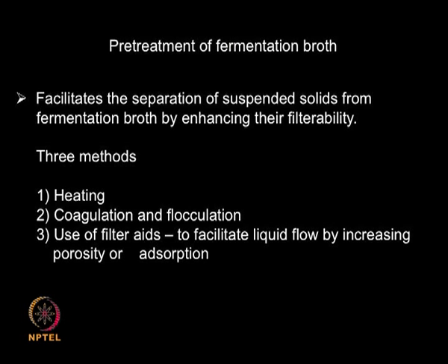This pretreatment strategy improves the filterability of the broth, because if you recall, after the fermentation the broth may be highly viscous, the broth will contain several types of particles, sticky particles, sand like particles, precipitated salts, dead biomass, metabolites. So you need to improve the filterability, otherwise the whole material may spoil the filtration unit as well as slow down the filtration process.